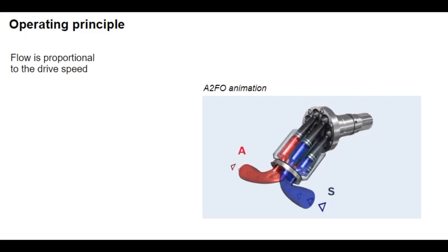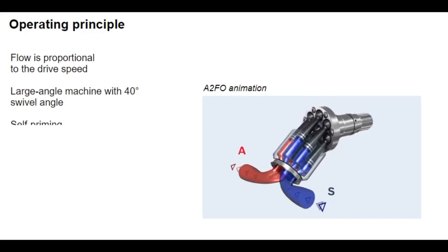The drive shaft is driven by the torque and speed of a drive motor. The drive shaft causes the pistons to catch the cylinder and rotate it. The cylinder slides on the control plate. With each revolution, the pistons extend into the cylinder bores. During one revolution, each piston returns to its initial position through the top and bottom dead centers. This causes the hydraulic fluid corresponding to the displacement to flow through the 2 discharge ports in the control plate.